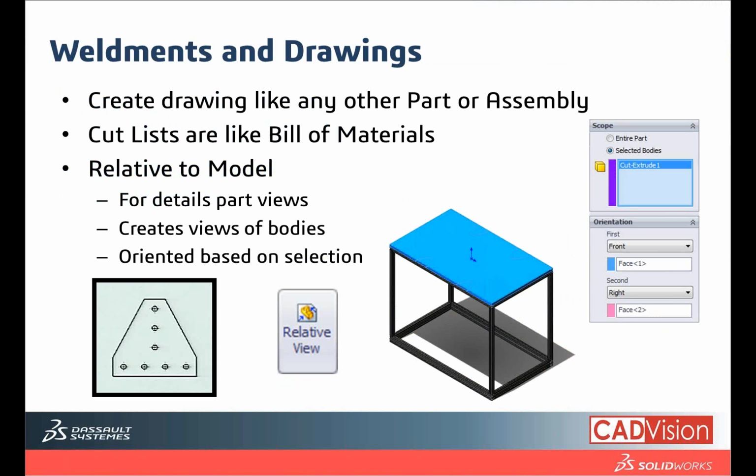We know what a weldment is. Weldment is basically to create a structural member frame, or structural members, in SolidWorks. If you check on the weldment, it will automatically bring you into multi-bodies. You will notice that the merge result is automatically unchecked. And how do you get the profiles? You can always get them from the 3D Content Central. You can either search for standard profiles, or search for the suppliers in the supplier list.